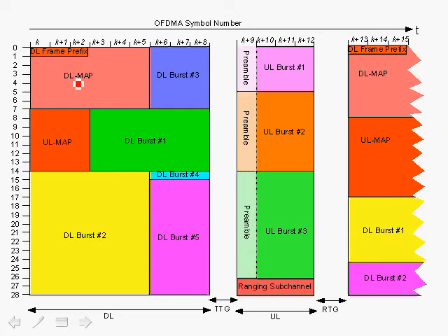I'm not going to go into detail of how these downlink maps are set up. Those will be described later, but actually they're set up through the MAC, passed through the PHY. The downlink map can actually be sent with a higher rate than the most robust rate, and that's one of the pieces of information that is given to the PHY by the downlink frame prefix, which tells the PHY what the rates are going to be for the downlink map.